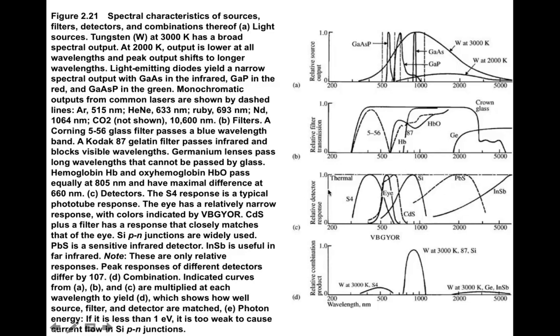But then the detectors themselves will have a response. So here's silicon. And silicon clearly peaks here in this region. So it'll have the strongest response to light of this wavelength. And of course, if you're outside of that wavelength, then you won't have any response at all.